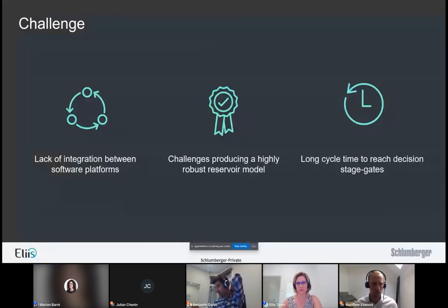Yeah, so with this workflow, I would say that we have two ways of knowing if the geomodel is refined enough. The first way is in the process of the interpretation. In PaleoScan, I didn't show it in the presentation here, but we have a preview. When we are in the process of doing the interpretation, we can display a preview before running the real RGT. This preview will let us know if PaleoScan does a great job or if it needs some help. So this is the first step, using the preview of PaleoScan. Of course, you can run the real RGT, but it will take a bit of time.